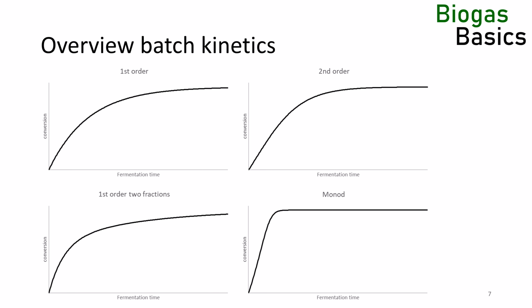The top right curve shows the gas production of a second-order reaction. The second-order reaction looks very much like a first-order reaction, but if the initial biomass concentration is low enough, it can also model lag and acceleration phases. At low initial biomass concentration, substrate is consumed but biomass is built up, so the reaction rate seems to be almost constant, leading to a sigmoidal or linear gas production.